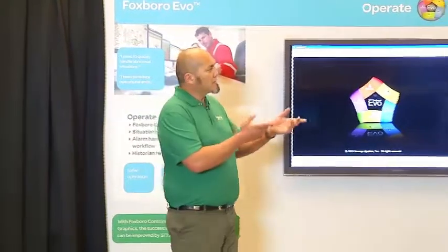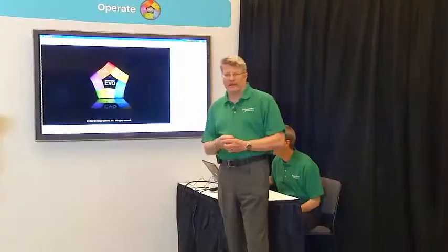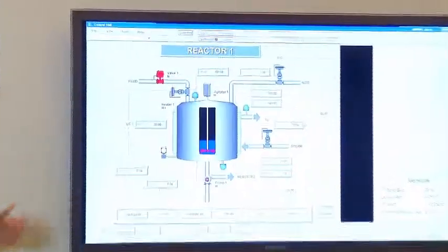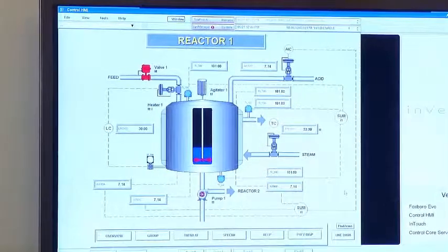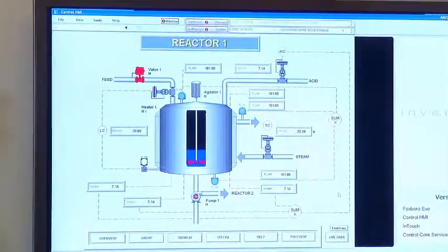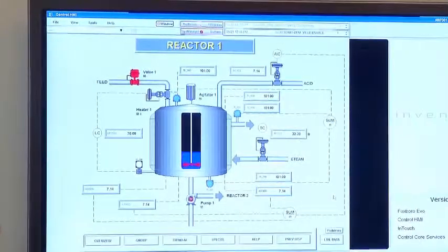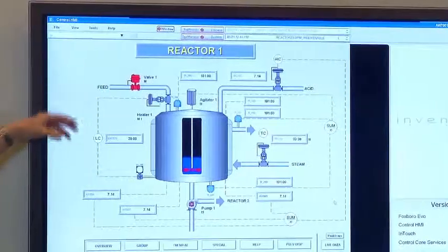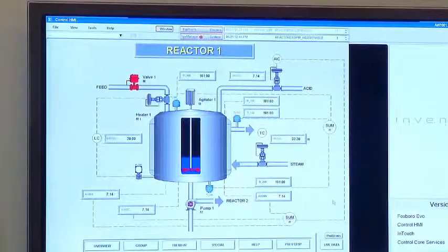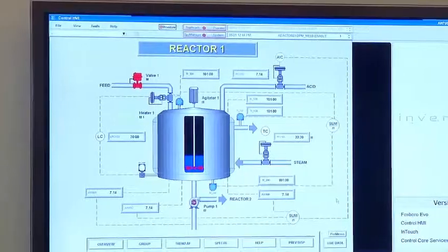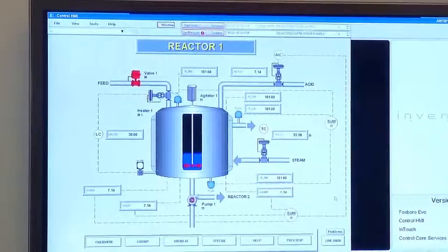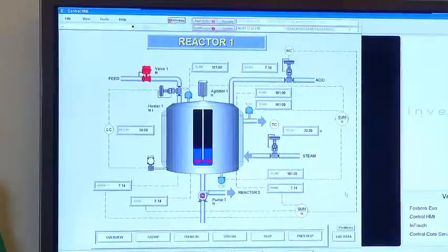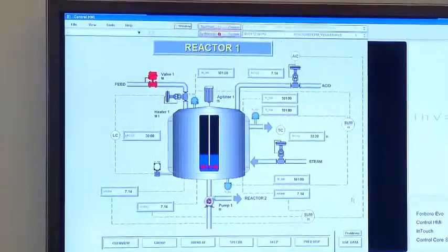Let's take a look at what we're doing at the HMI level to help the operator be successful. Marcel. What we see in existing plants is displays like this one. We visualize the plant, we visualize a P&ID scheme, and we use all the nice features that we have in our technology to show cosmetics like this beautiful valve, like a three-dimensional display of the reactor of the plant equipment, and we use color. Now the problem is that this information really doesn't help the operator, it just decorates what we show on the screen.